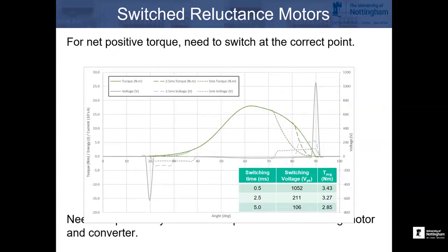We talked a little bit about switching behaviours. So if we want to actually make this into a real operating machine, you can't just constantly activate those poles because, as we've shown, you get net zero energy, net zero force. So to actually make a working machine, we need some way to control the magnetic field, and ultimately we need a way to get rid of that stored magnetic energy in a way that isn't going to produce equal amounts of positive and negative torque. And this highlights some of the challenges, although it slightly impinges on the field side: how much time you've got to get rid of that energy, how much stored energy you get, some of the issues there.